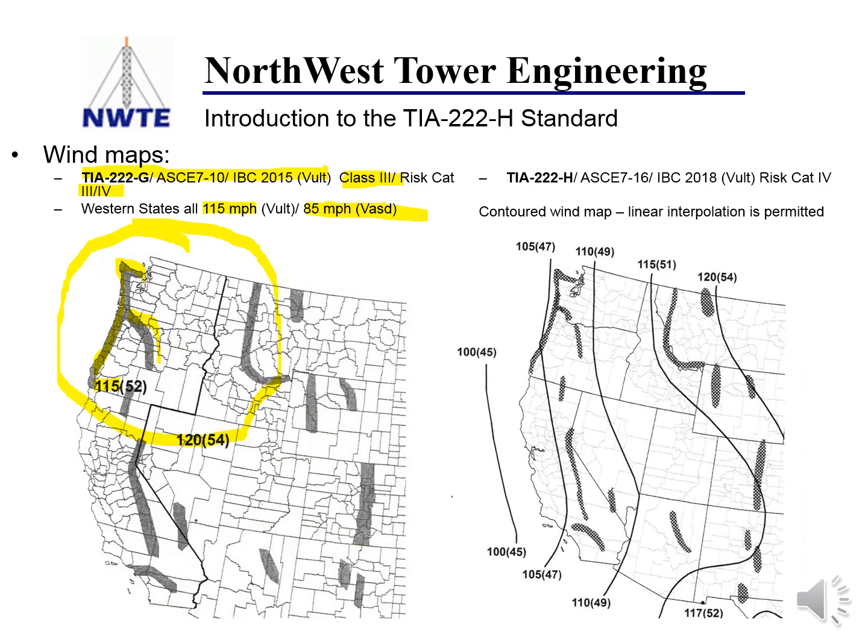If you were in Oregon, they had a specialty code where they actually increased those wind speeds. Now this is quite different under the H standard. Here we go. So this example is risk category 4. There are separate maps for every single risk category. This is the most onerous with the highest wind speed. So you see it's 120 over this end.